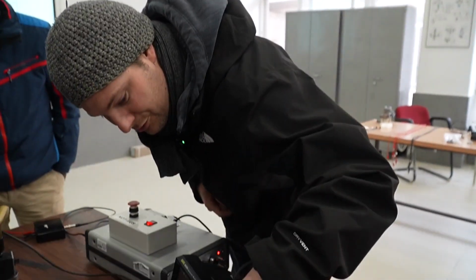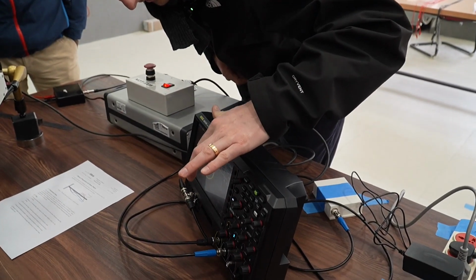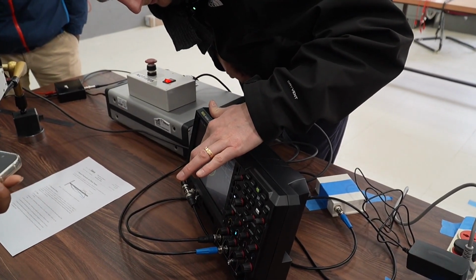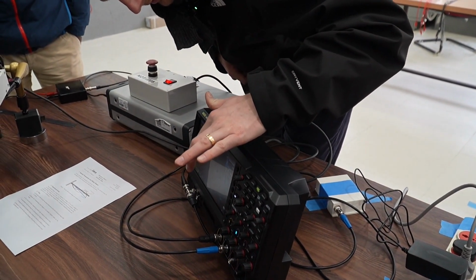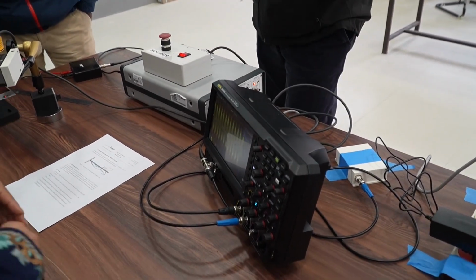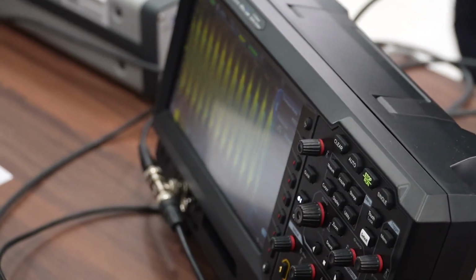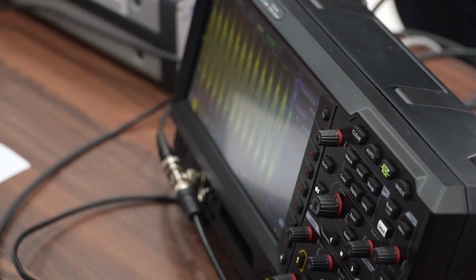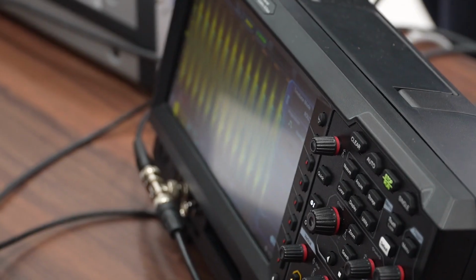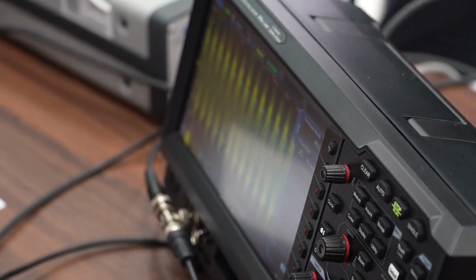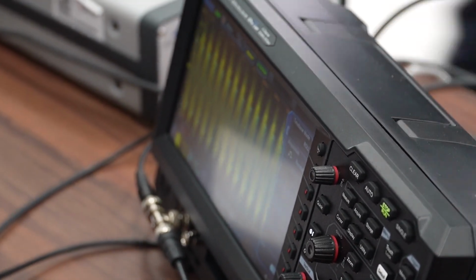I suggest to go to acquire and to start in the time-based signal, maybe again with rho. And I also tell you right now, you probably have to look somewhere above 40 Hertz, otherwise we will search a long time for the second eigenfrequency. So maybe start from 40, looking for the second eigenfrequency.